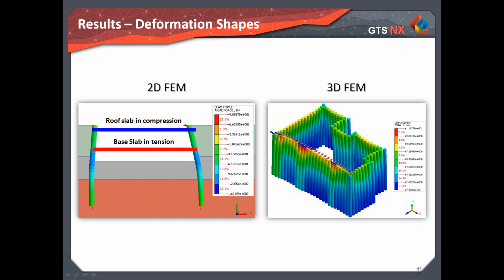This situation is due to the deformation shape of the walls and slabs as one structure when subject to line and moment loads at the piles in an asymmetric profile. Limit equilibrium model assumes a symmetrical behavior and ignores the 2D geometry of the structure along with the associated load path.